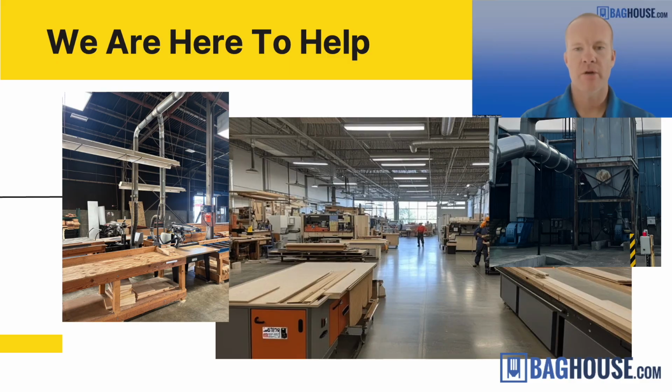It's just about figuring out the system size, designing the ductwork, figuring out what the combustible dust requirements are for that system. If it's a big system, we may look at putting a cyclone as well as a fabric filter system, and then we hand off a turnkey proposal for you as a customer to review. So that pretty much sums up the design approach, the elements of that, combustible dust, all that stuff. So I think at this point, Andy, we're going to move over to Q&A.